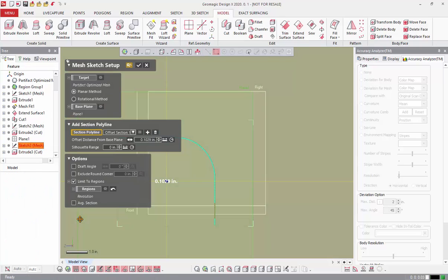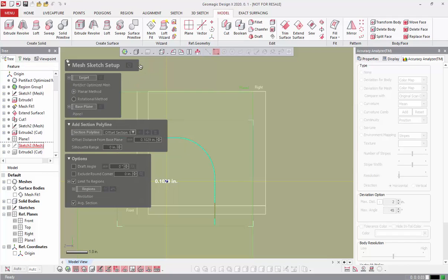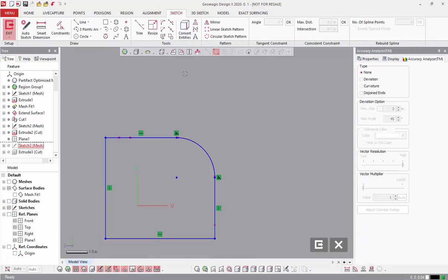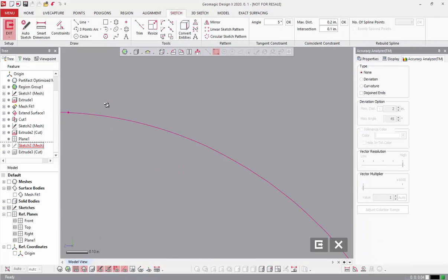So if I edit that, average the section again, it just mashes all of those individual cross sections into a single one at the average, which is much cleaner and much easier for the software to use the auto sketch command to sketch those features. Okay.